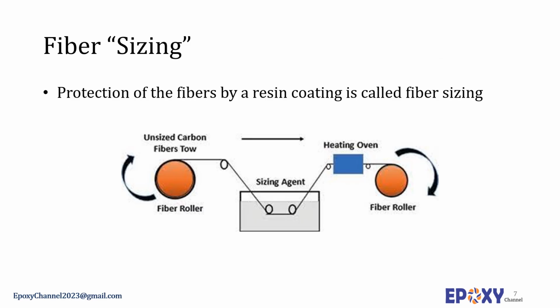It is also worth mentioning that the filament strength is larger than that of the bulk material. However, the strength of the filament is still determined by the presence of defects, and therefore the reported values are gauge length dependent, meaning that individual filaments within the bundle will have a different strength. This also highlights the need for the protection of the fibers by a resin coating, or so-called size, during handling, immediately after manufacturing. For this application, emulsified epoxy resins are commonly employed for carbon and glass fiber.